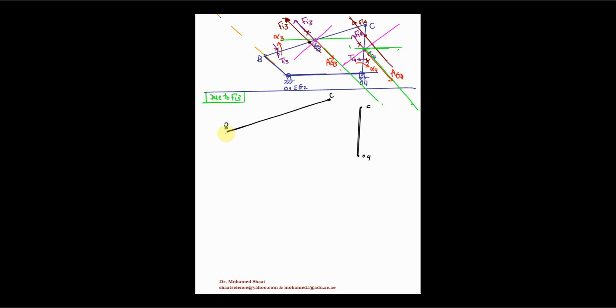Then you're gonna move with the same opening of the compass to this point, fix with the metal tip here, then cut an arc here to locate this point of intersection. Remember that this point is not point G3. It's different. It had been shifted with H. So your objective is just to locate this point over the link. It's gonna be this point.